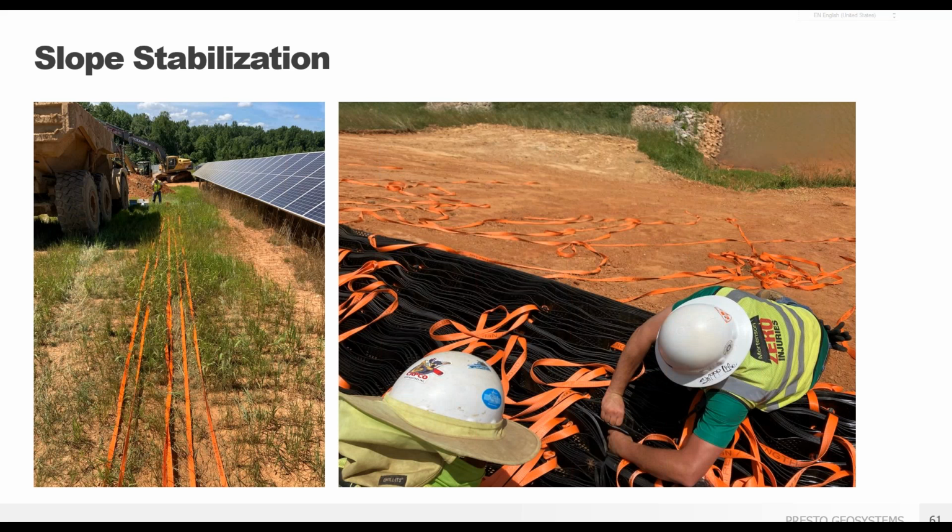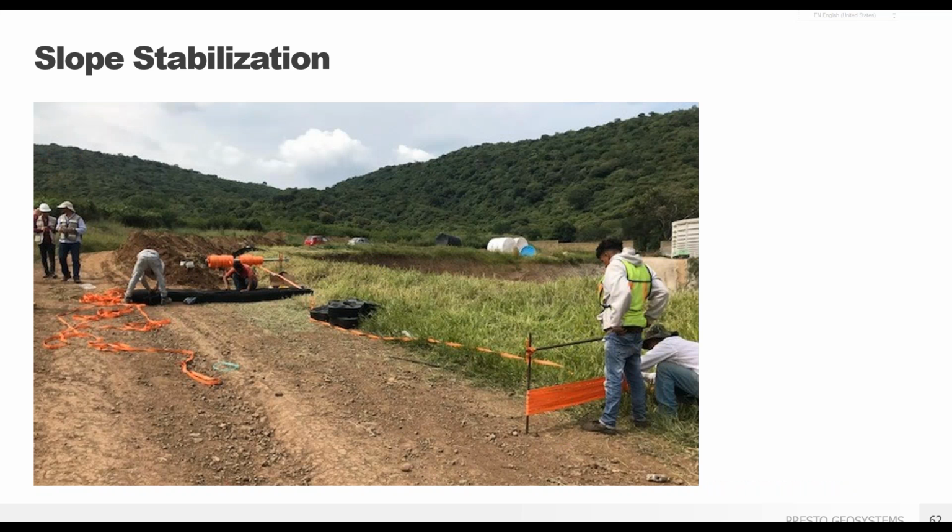Tendons were laid out, measured, and marked per design, then inserted through the eye slots on the slope crest, with sections being built on this flatter ground where it's safer and easier to work. A suspended rod through the tendon spools is a good technique tip that can be helpful when marking and inserting the tendons.